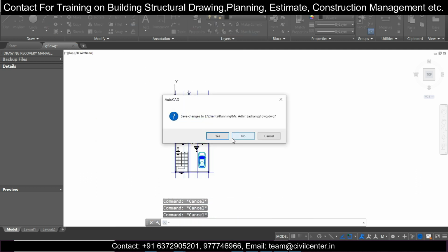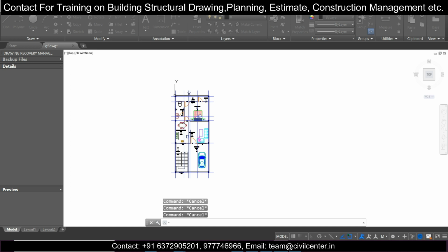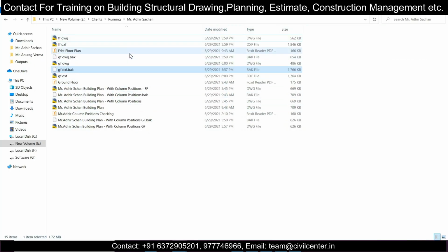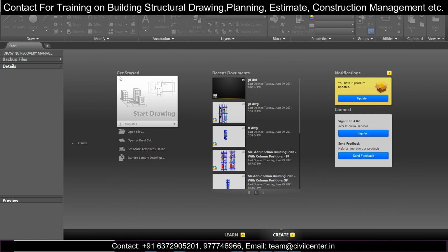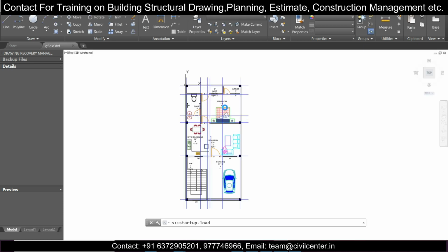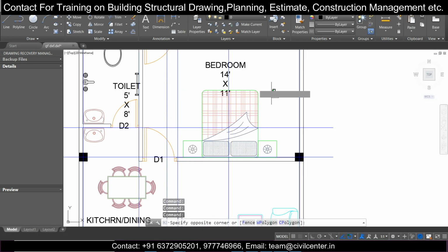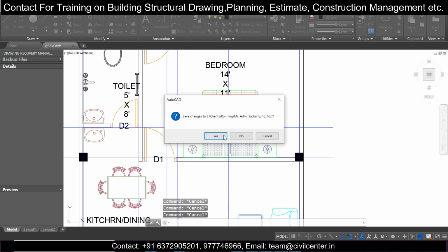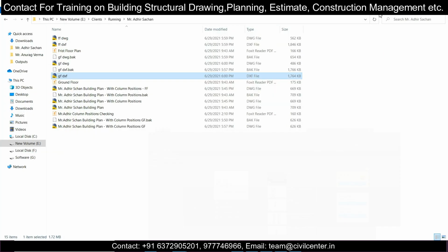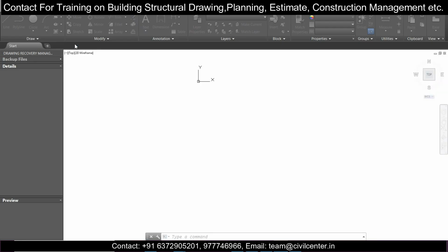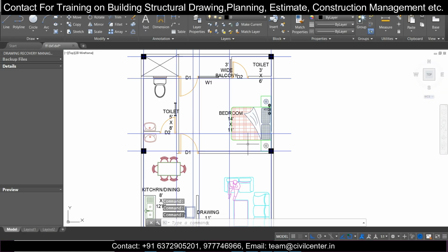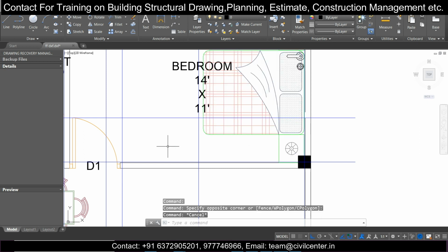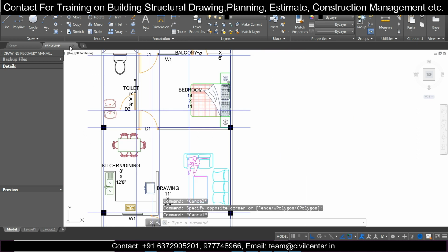So here you can close this particular file, and you can check the 2 DXFs before importing it, GFDXF. As you can see here, this is a GFDXF file. Furniture is in 0 layer, center line is in CL layer, and you can close this. And after that you can also see the FFDXF file, just checking before importing in Tekla. So check the furniture, it is 0 layer, and the center line is center line. So we are good to go.